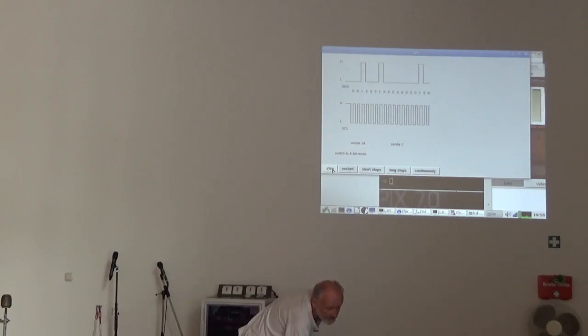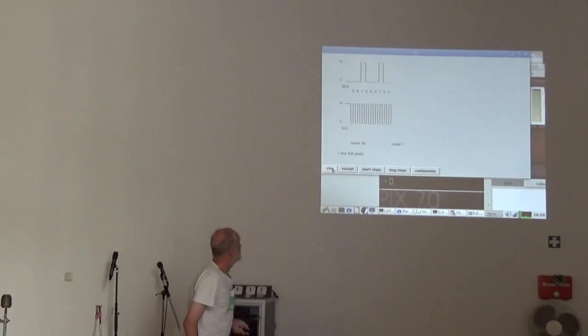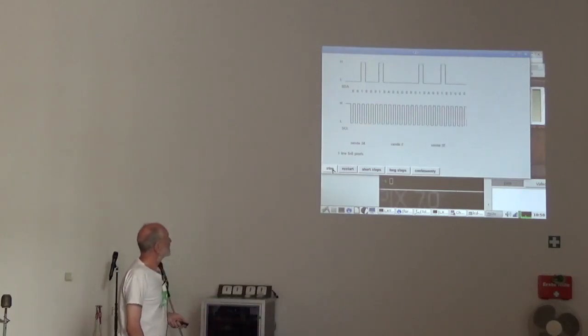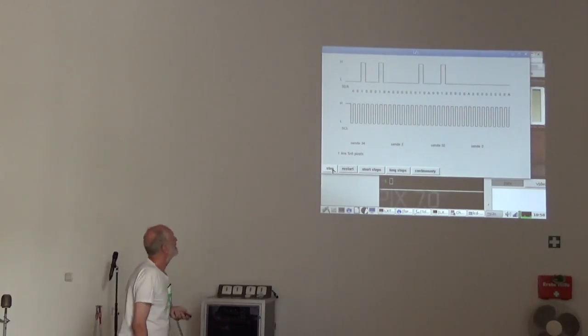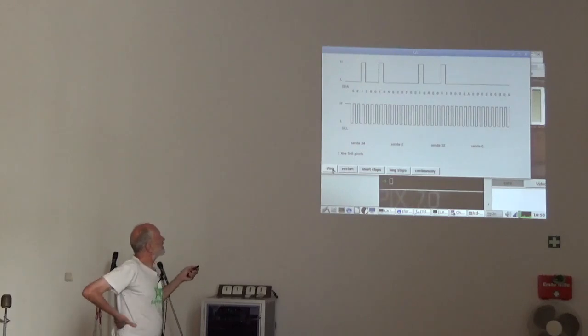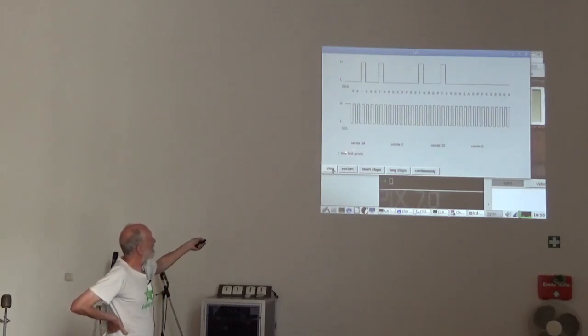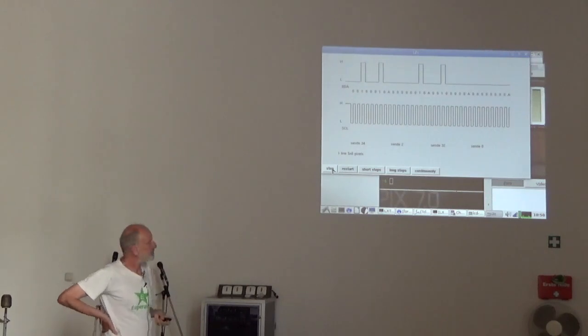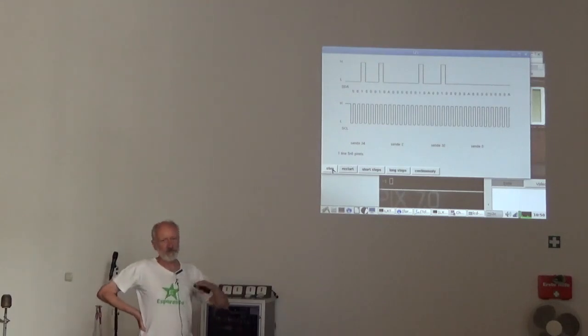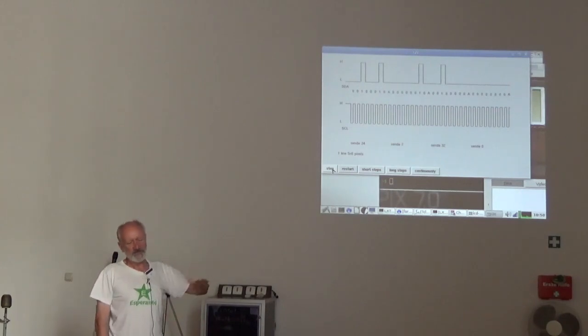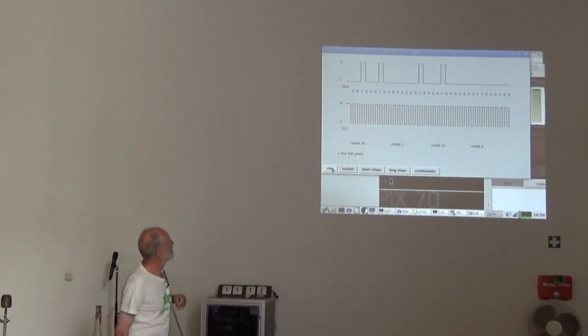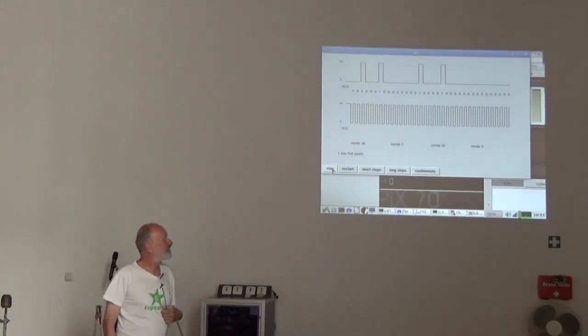Then it will switch to one line, 4 times 8 pixels. And by the way, for one instruction I always need to send 4 bytes, because I must toggle the enable bit, because a command is only taken when the enable bit is falling, I think.